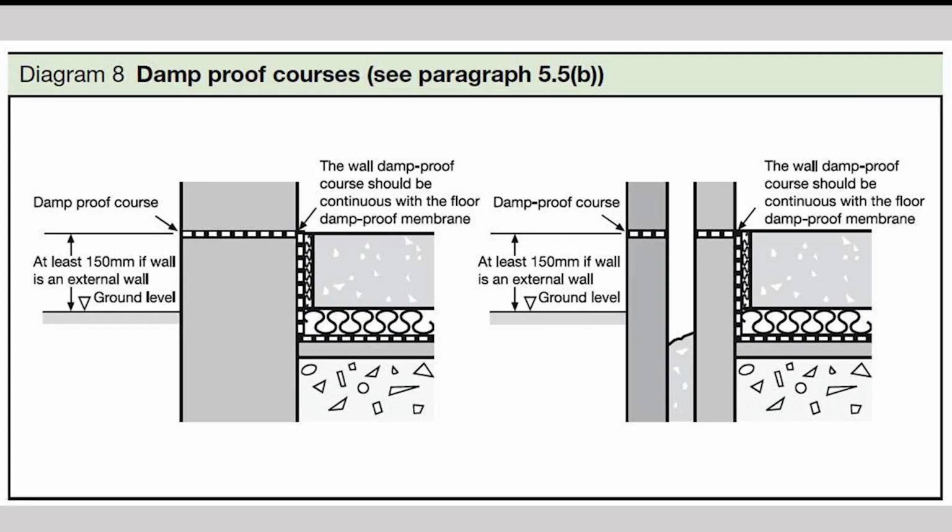Okay, yeah. Now that can be done through simple pipes in inverted commas, or cranked air vents that go through the cavity and down. If you are breaching the cavity itself, then you'll need to have a tray over that, and that's an important part of the detailing of damp proofing, and that's where really part C comes into huge effect. A lot of people don't really understand about the detailing of damp proofing. So you can have air bricks that are running through, you could have services that are running through.